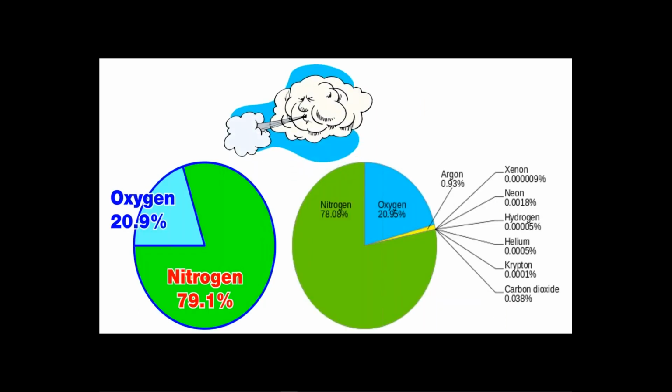So there's oxygen at 20.9%. That's what's in our air that we breathe. So when you first turn on your analyzer and it's doing an ambient air level, not temperature, but level, you will see that number come up darn close to 20.9. That's the amount of oxygen in the air that the analyzer is taking the sample of, in ambient air, that is. And nitrogen, 79.1.